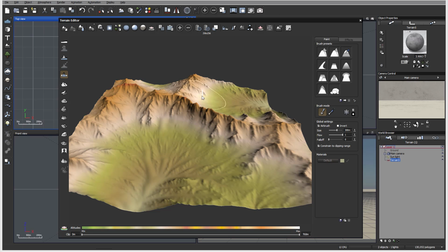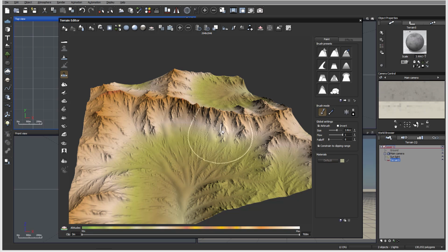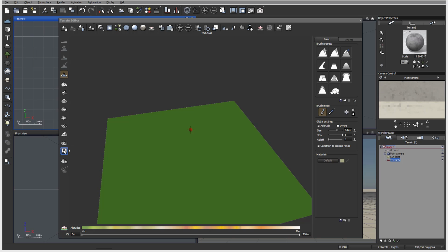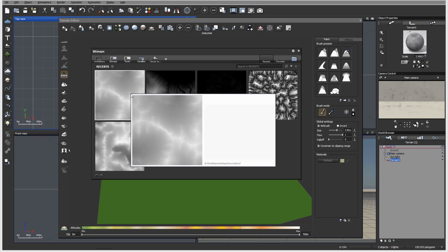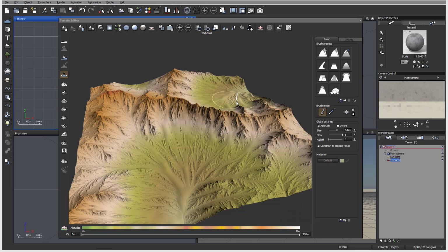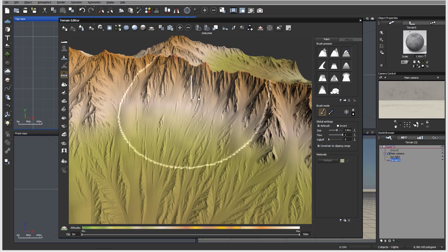So you want to at least match the resolution of your terrain. So I'm going to increase it. I'm increasing here afterwards, but you can see it's a little bit sharper, but still has all this pixelization. And the reason is because when we loaded the map, it was already applied to the height field at this point. So if I reset it and go back and select the same map, the height field one, okay, let's click OK. Now you can see how high resolution it is, because now we have more pixels applied.